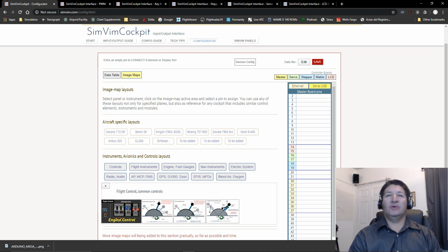A digital output is, for example, a single LED or a serial LED driver, like the DM13A that I just did a video about recently. Analog inputs are like potentiometers, whether they're rotary or linear, and also photoresistive sensors, which are light sensors, so that you can send a signal into the Arduino depending on how much light they're sensing.